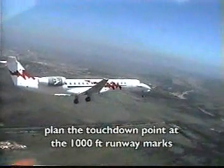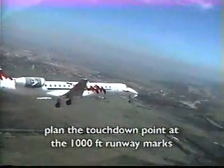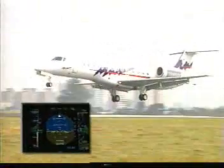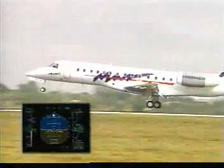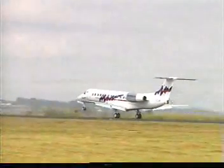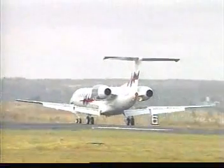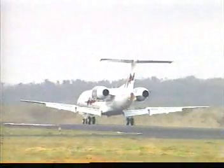Plan the touchdown point at the 1,000-foot runway marker. Do not permit the airplane to float during the flare. Using a normal flare technique as the airplane approaches the touchdown point, reduce the rate of descent by increasing the nose-up attitude and slowly reduce engine power in order to achieve idle as the airplane touches the runway. Normally, a 2-degree or 3-degree pitch-up change is required to reduce the rate of descent during the flare.